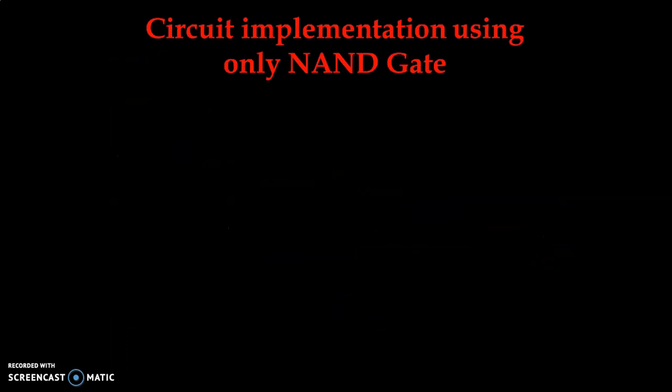Now let us take another example, then it will be very clear. Now we take one switching function, that is f is equal to A bar dot B dot C plus A dot B bar dot C. Again, in the given switching function we have 2 product terms and both the product terms are added together. So it is an SOP type of Boolean function, and we can implement it with only NAND gates.